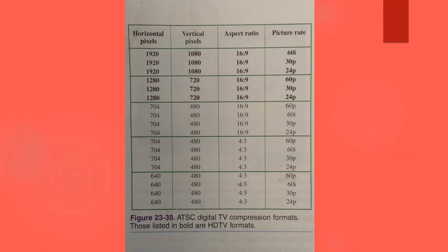The compression technique is based on the fact that the majority of the video images on a television screen do not change from frame to frame. For example, a news broadcast has a persistent image, such as a background, with very little movement requiring new data. Parts of the image are persistent and do not need to be broadcast in each frame. This reduces the total amount of image information that has to be transmitted. The same technique is used for DVD, CD-R, RW, and still cameras.